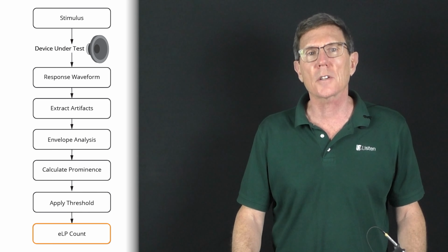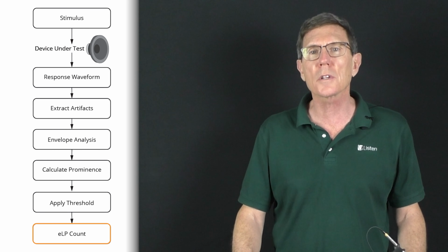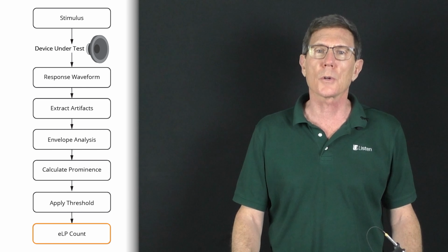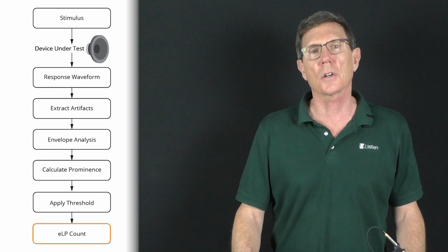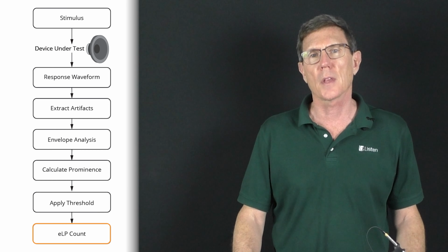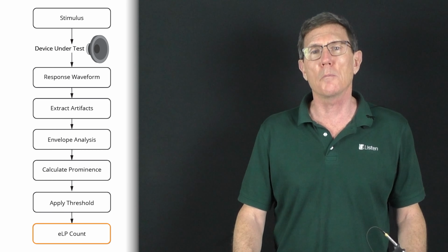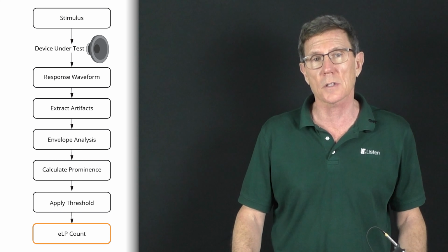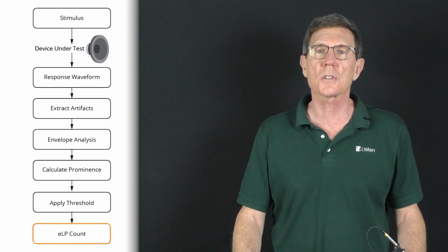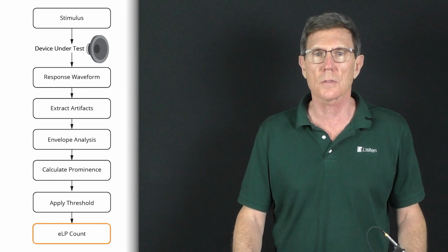Typically, factory background noise events only occur once or twice during a quick measurement, whereas many loose particle transients will occur during the same time frame. So we can set the event count minimum to exclude infrequent transient background noise events to get reliable results under a variety of conditions. So that's how it works. Let's just summarize the benefits.